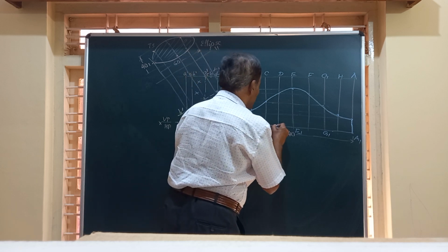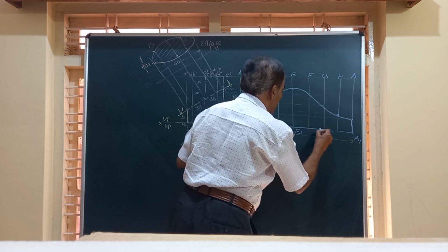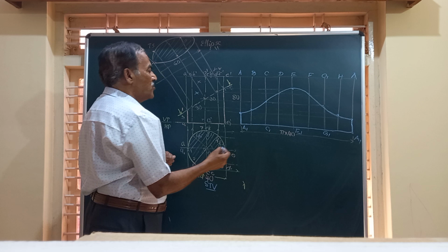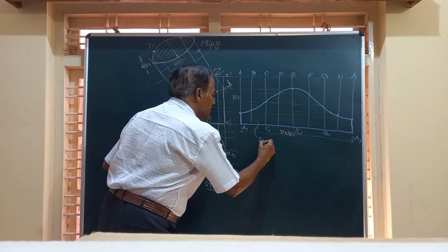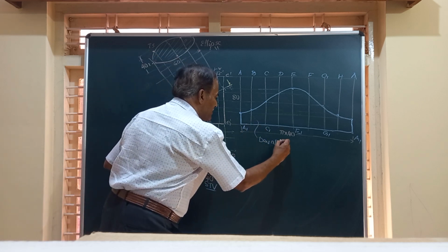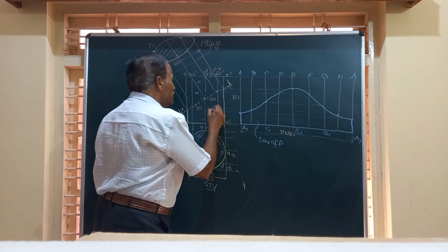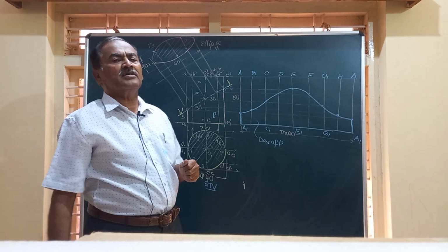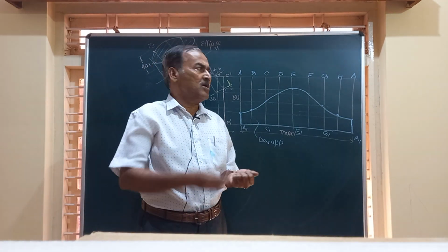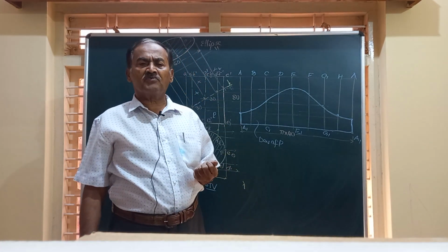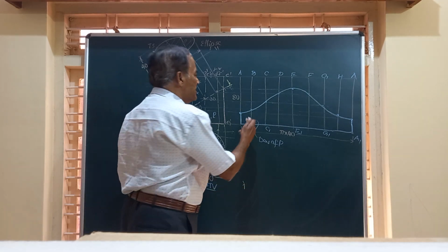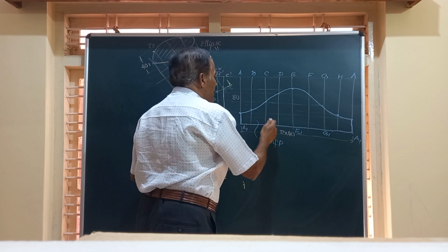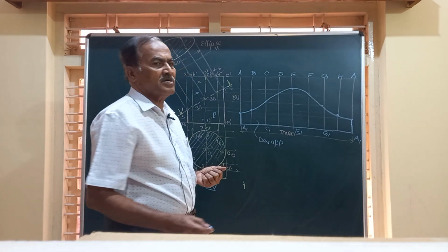So we will show the base of the cylinder, bottom portion of the cylinder by this, and this is, friends, how the development of P, where P is the lower part of this. So this is the development of P, that is the development of the lateral surface of the lower part of the cylinder.